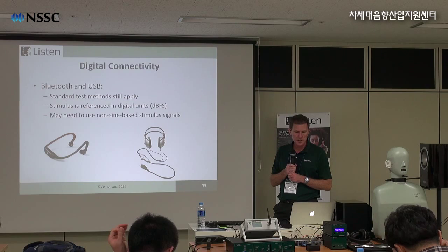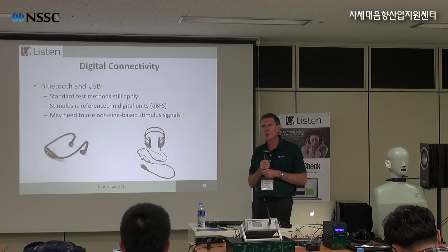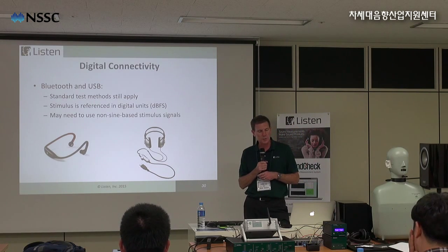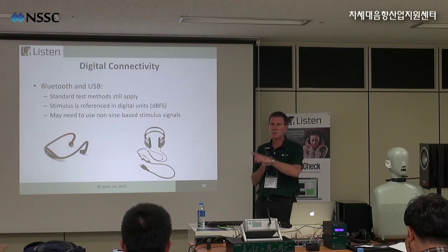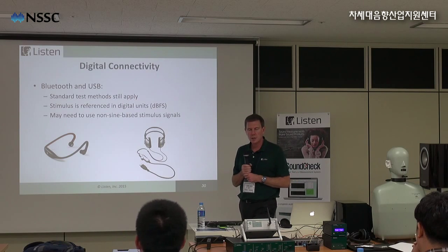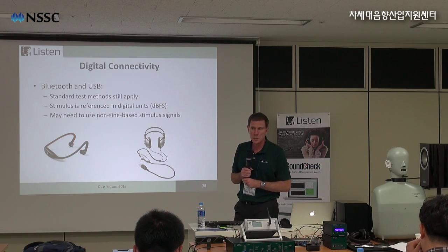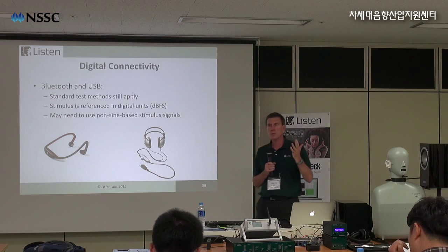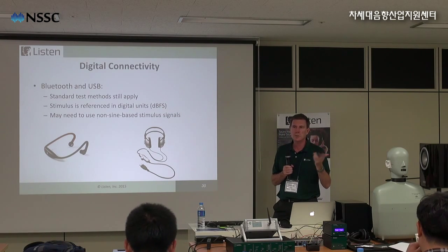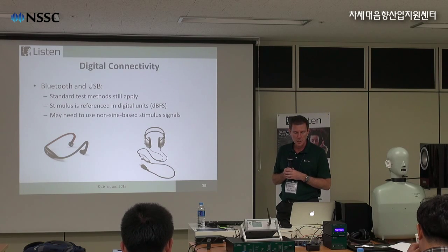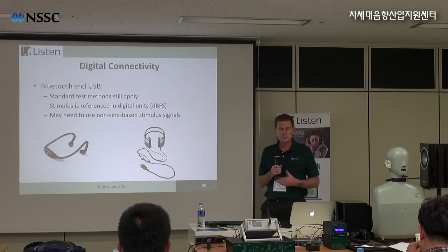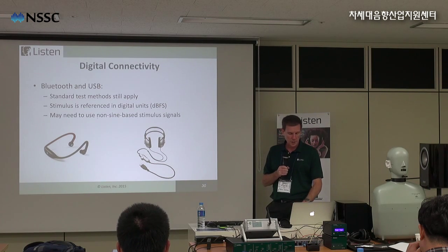Some headsets, you have to be a little careful with sine sweeps. Bluetooth is notorious for having dropouts. So we've actually, Mac will show you this in a moment, we have a calibrated Bluetooth interface with a high output power to minimize any Bluetooth dropouts due to the connection. But sometimes it's a good idea to also try things like multitone or noise as well. So just something to be careful about.